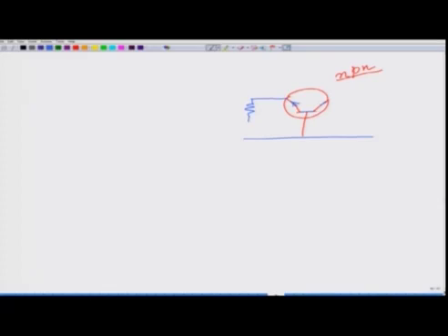Now, how do I put my battery, which side positive, which side negative? Once again, this input side should be forward biased. This junction, the PN junction between the emitter and the base here, this is the input side. So, this should be forward biased, and this is N, this part is N, NPN. So, this should be negative and this should be positive. This is how the battery should be connected to make it forward biased.